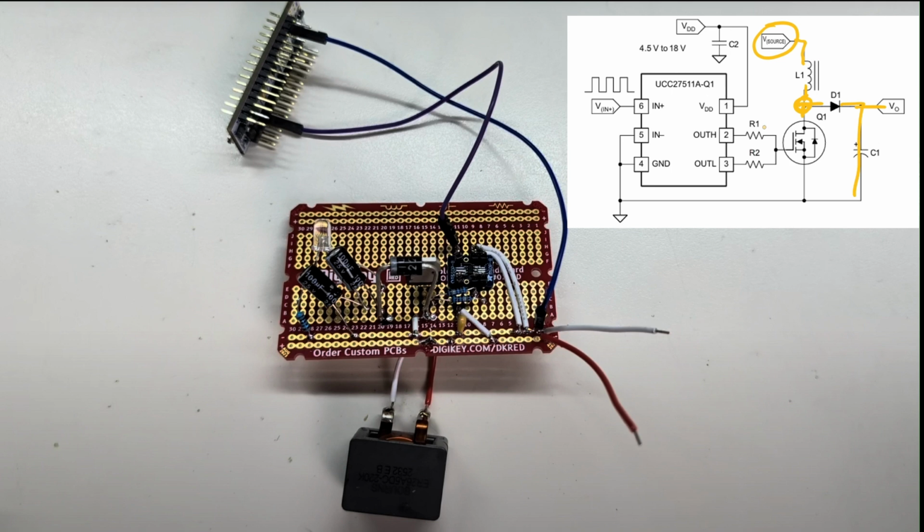And then of course, you see these resistors here for the gate driver. They're going to control your on and off time. I just put 2 10 ohm resistors, but they're here and here, and they go into the gate, which is the first pin, right? I hope you can see this. And then for the ground, you can see pins 4 and 5. They're these white cables here, and I've just looped them straight to ground. I could have put the ground on this, but I would have had to do double the work.